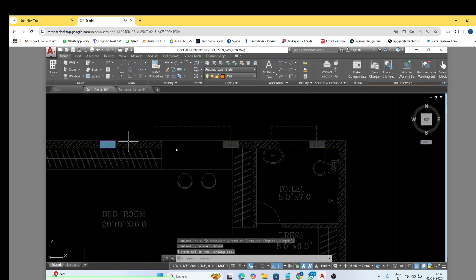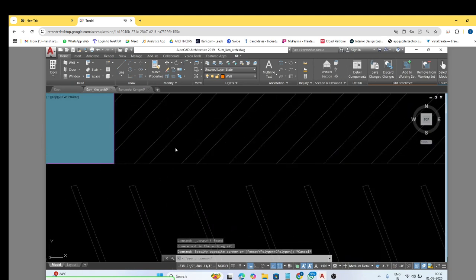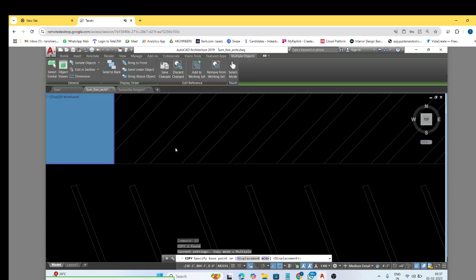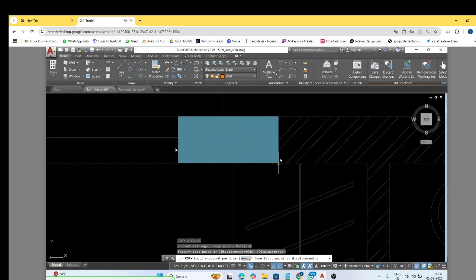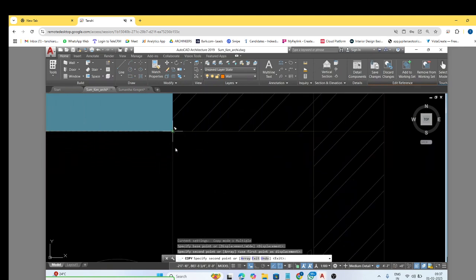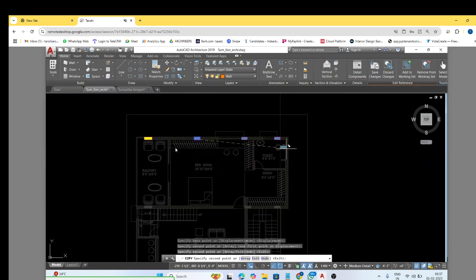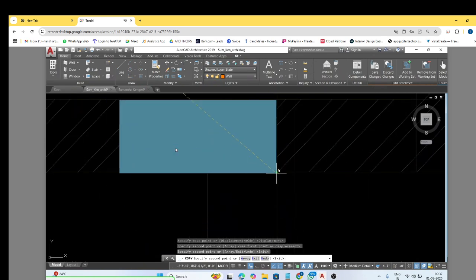Use a horizontal. Always ensure, because once you place the columns like this, I will never get to know what was the actual position of the columns. While placing the columns, be double sure that you are placing it properly. If you make even one mistake, all the other work will follow the same mistake, which we can't even identify in later days.